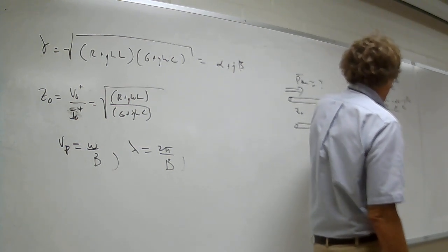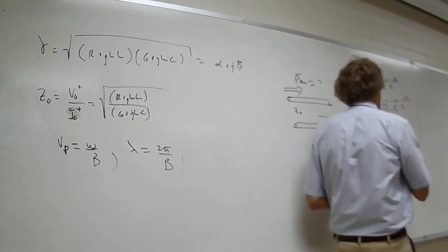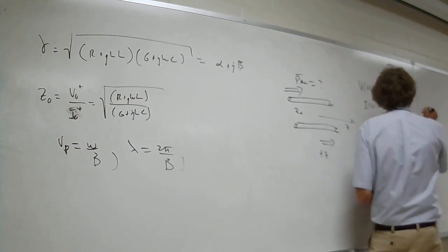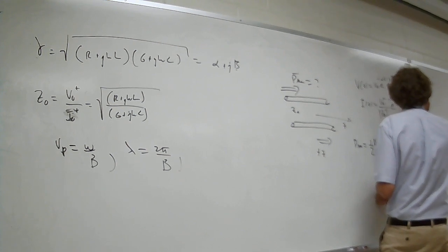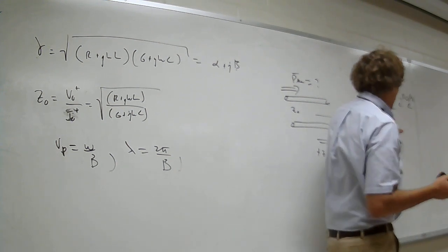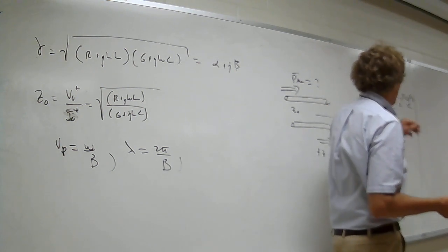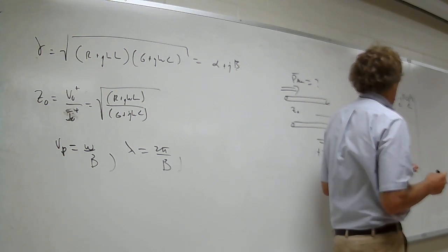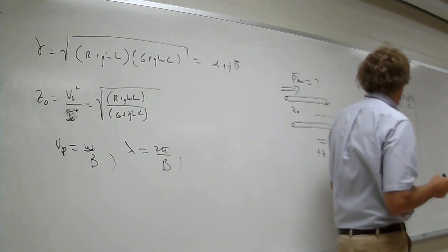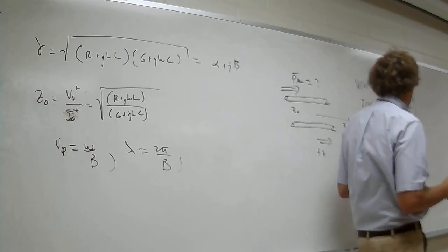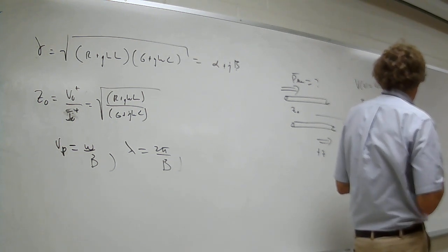We did this and we mentioned that for I conjugated, Z naught has a magnitude and a phase angle. The phase angle would appear as minus j theta Z here because when it's downstairs, it would be plus j theta Z. If you take it to the numerator, it would be minus j theta Z. And then when you conjugate this, the two complex components change sign and become positive.